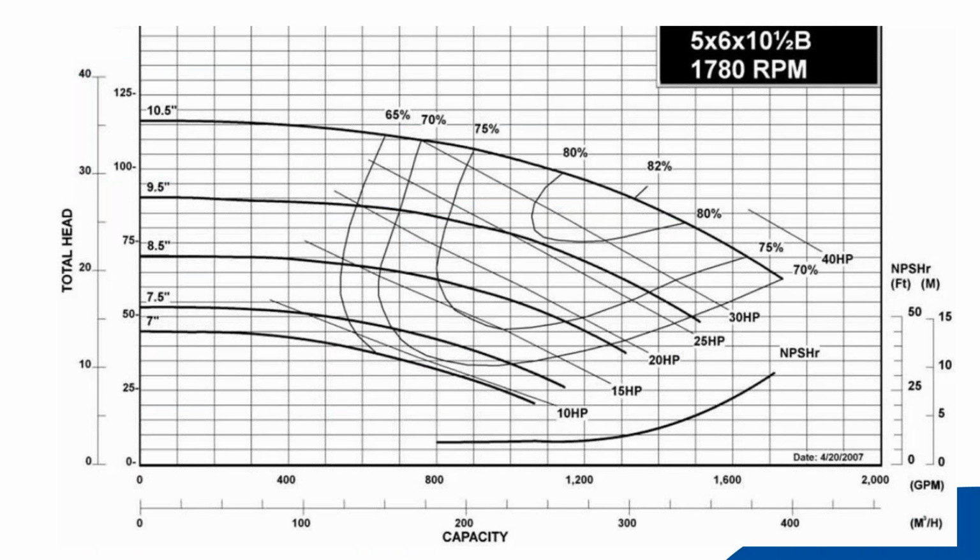So here's an example of a real pump curve. This is what I was talking about, that all of these things are functions of flow or capacity, but they're also functions of impeller size, and those are related via the affinity laws. I can't get into those, so watch Back to Basics if you need to know more about affinity laws. What is shown here, though, that I do need to talk about are the efficiencies. They give almost like a topographical map, right, for each impeller size, giving a region.